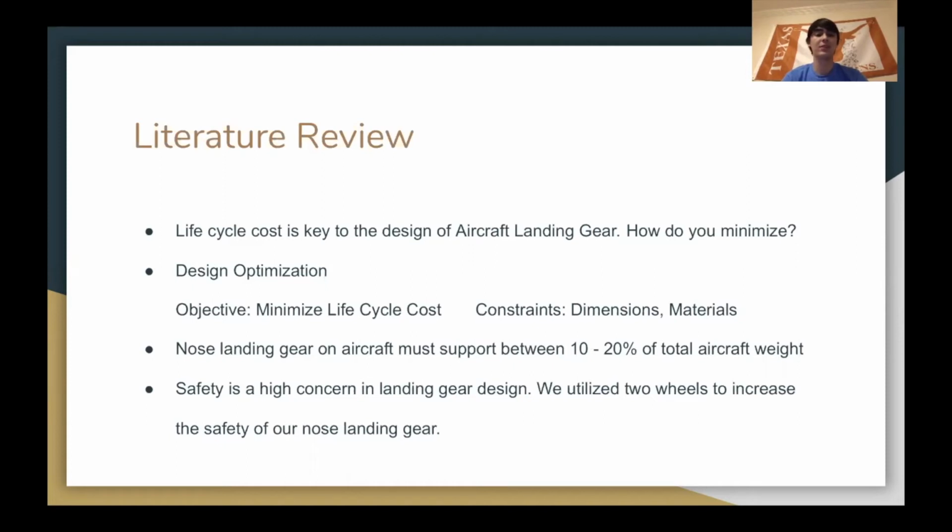You can lower the percentage of the aircraft weight that the nose landing gear needs to support by moving that nose landing gear further forward. Since we don't have an actual aircraft to model off of, we just chose to use this 10 to 20% range for finding the weight and the load that our landing gear needed to support.